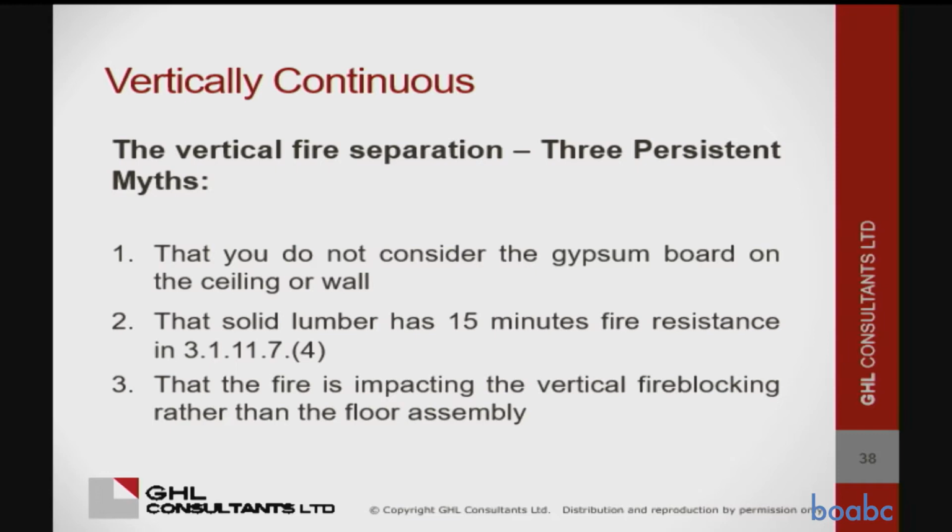And then it says a 38 millimeter member can be used as a fire block. But we don't take those two things and add them together and say, oh, that means that a 2x10 has a 15-minute fire resistance rating as a fire block, because it's probably much higher than that.